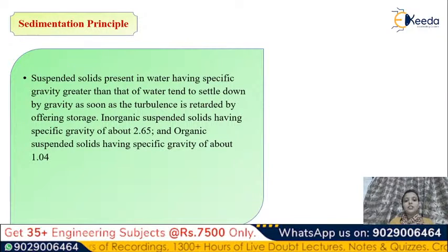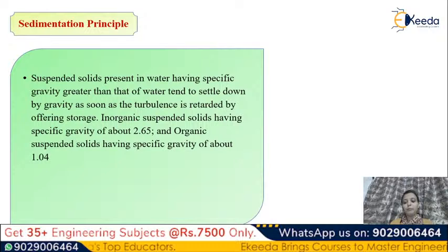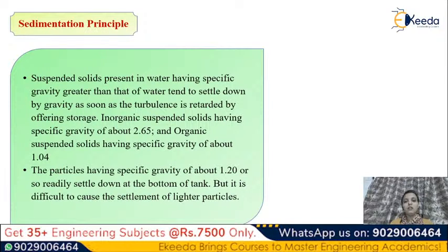Inorganic suspended solids having a specific gravity above 2.65 and organic suspended solids having a specific gravity above 1, that is greater than the specific gravity of water, all those particles settle down in the sedimentation process. So what is the principle? Sedimentation is based on which principle? There are two important keywords. First is the gravitational force and second is the specific gravity. So it is based on the specific gravity of the particle.